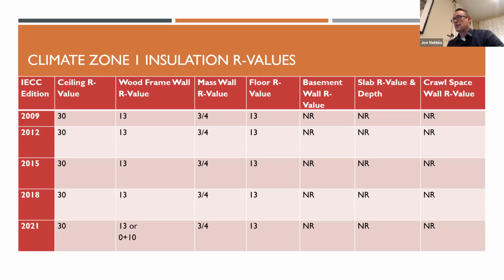More than 50% to the inside, you have to put in an R4 as a minimum R value. So that's like an inch of EPS foam, maybe a little bit less than an inch of XPS foam, just to give you some context for how much insulation that is. And it's an assembly that we see a lot in Southern Florida.